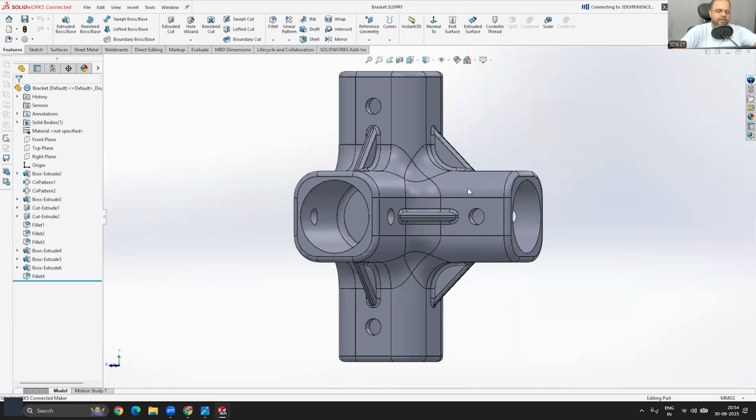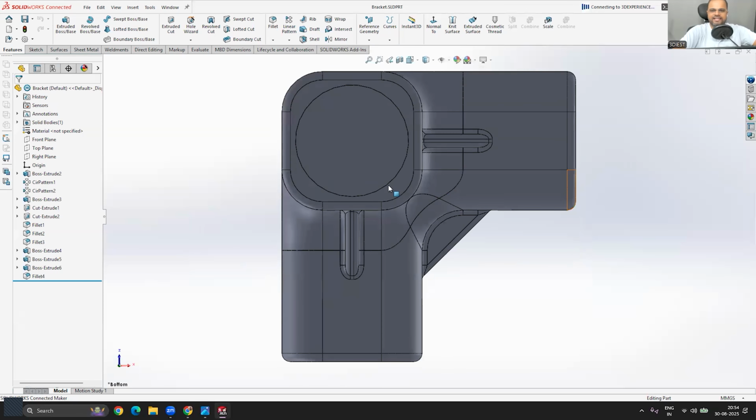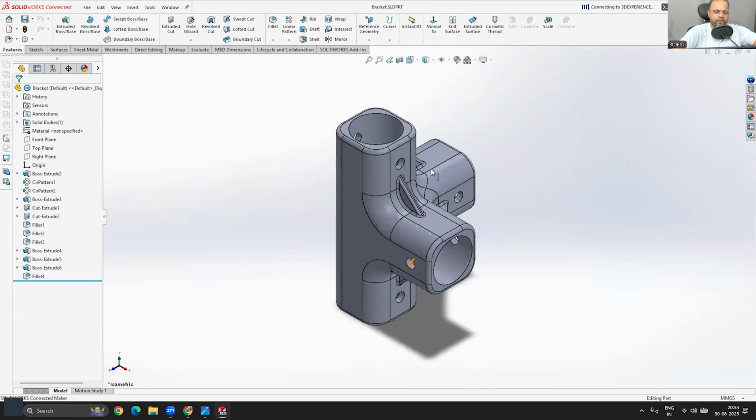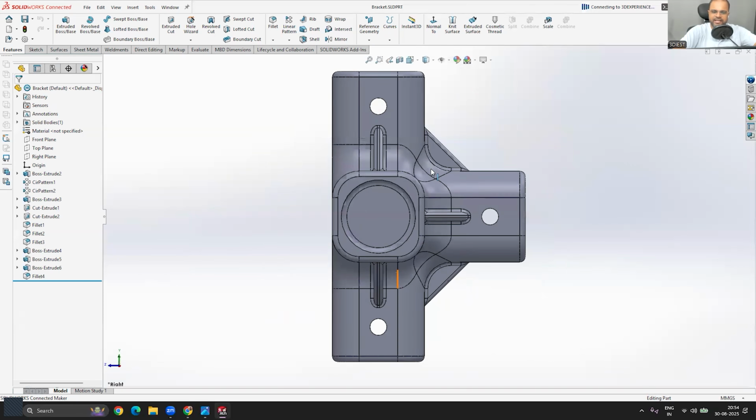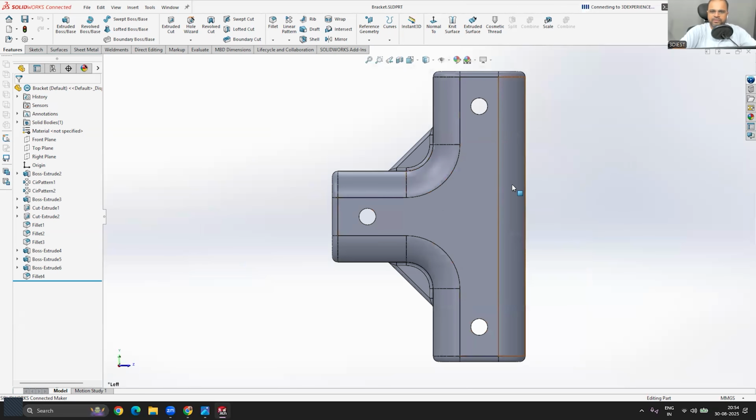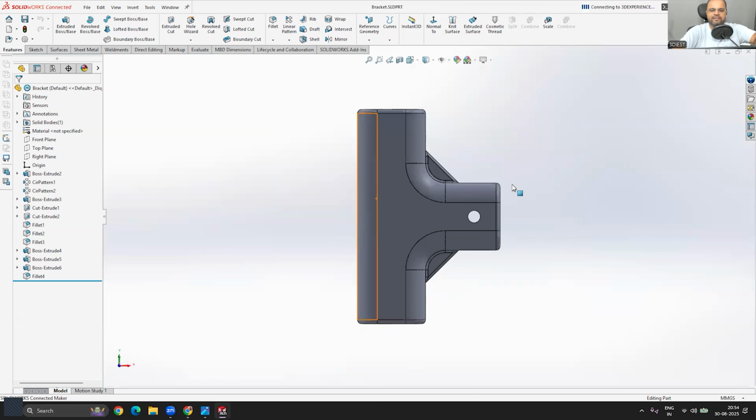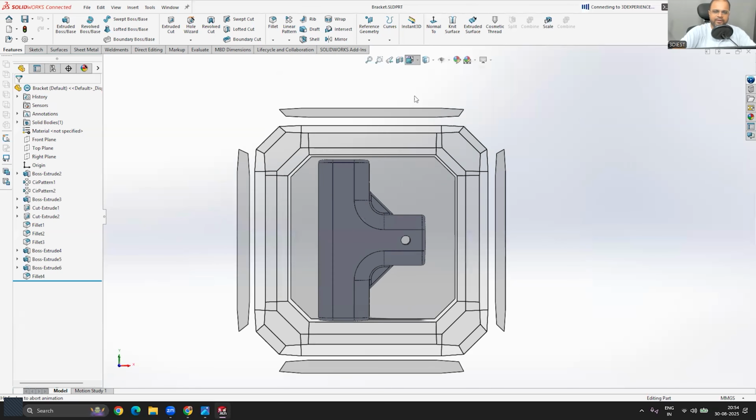So you have to remember these settings so you can easily navigate across your 3D model from your keyboard as well. You can quickly change the orthographic views of your model inside SolidWorks using these keyboard shortcuts. Super easy, right? Here you can see. So that way you can control the things.